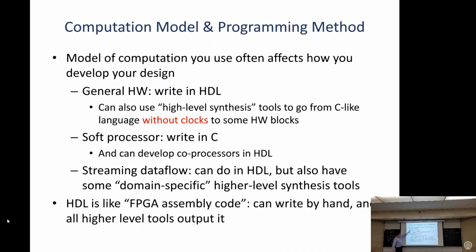So if you're doing general hardware, just hardware that's got all sorts of things mixed together, you're not quite sure what it is, the hardware description languages are the most powerful thing. Often now, but not always. For high-end systems where people need a lot of throughput, they usually write it in HDL. If they need to get something faster, they will often write it in high-level synthesis. Sometimes they'll write some blocks in HDL, some in high-level synthesis.